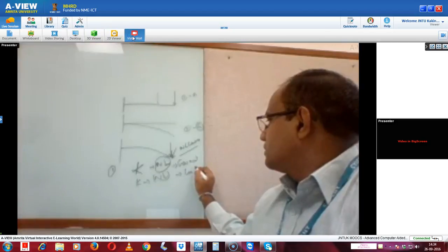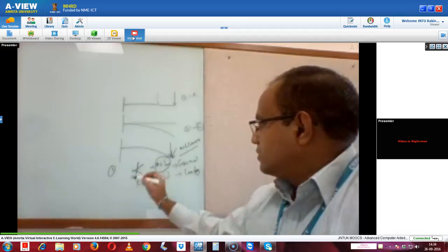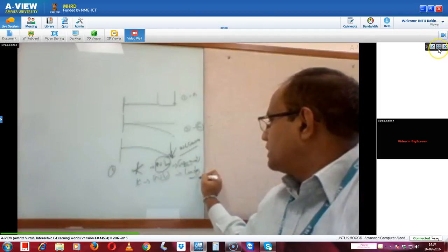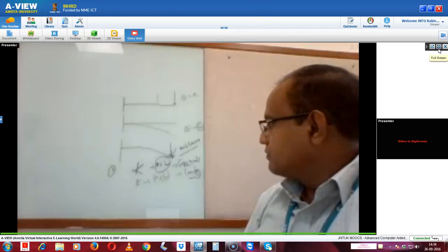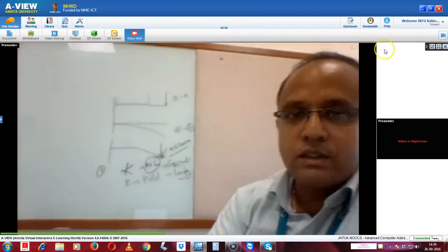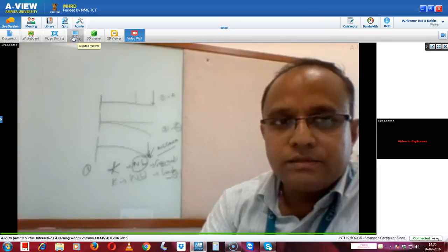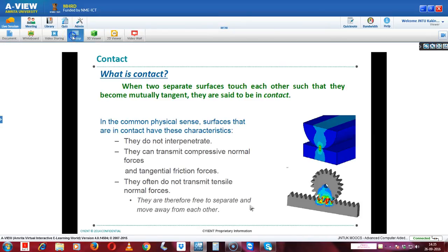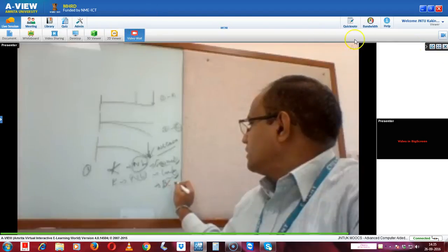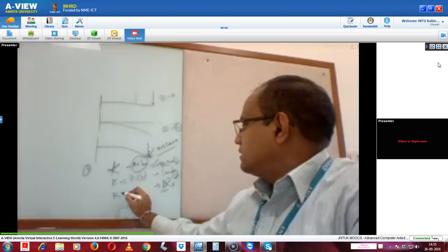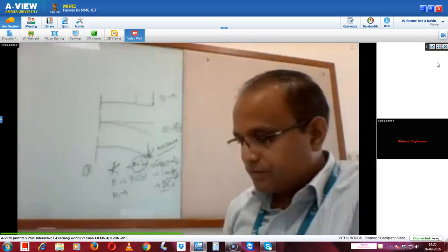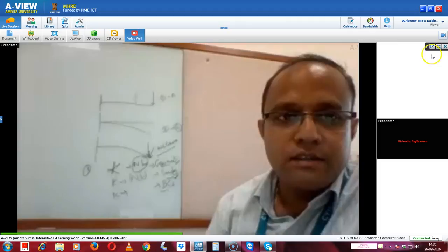Loading. Okay. So one is because of geometry, one is because of loading. Let us understand one more nonlinearity, that is contact, also known as changing status. One is on geometry, one is on loading, another one is boundary condition. That is contact. So let us understand what contact is.